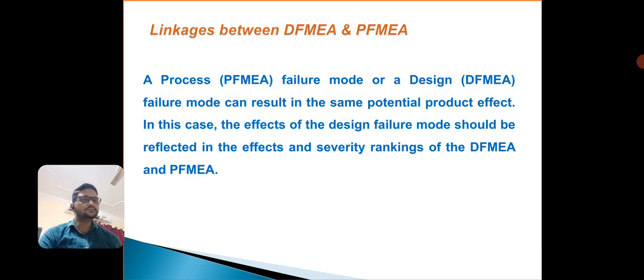Actually a process FMEA, that is PFMEA, or a design FMEA, that is DFMEA, can result in the same potential product effect. In this case, the effect of the design FMEA should be reflected in the effect and severity rating of the DFMEA and PFMEA also.